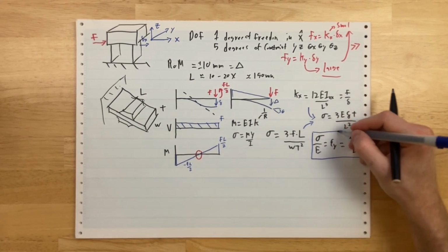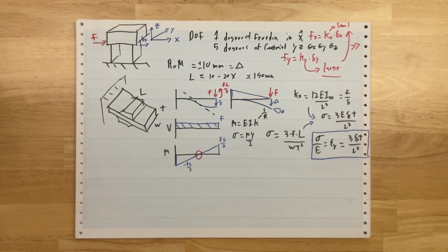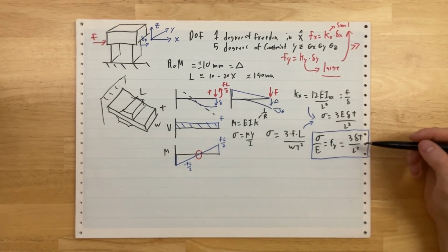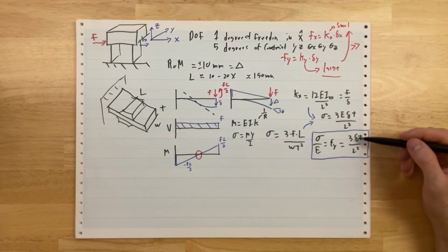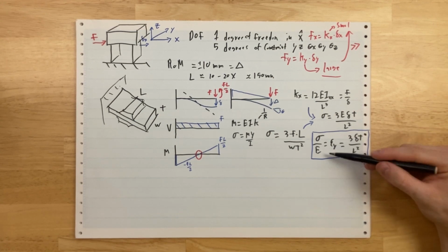Geometrically, we are bending this shape. It requires the material to strain, and we want to keep it in the linear regime, otherwise it'll yield and kind of fail over time. So the more we move it, and the thicker it is, the higher the strain. If we make the beam longer, the strain goes way down. It's easier to bend. Fundamentally, how do we choose this number?